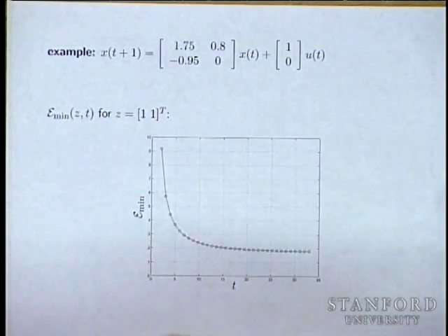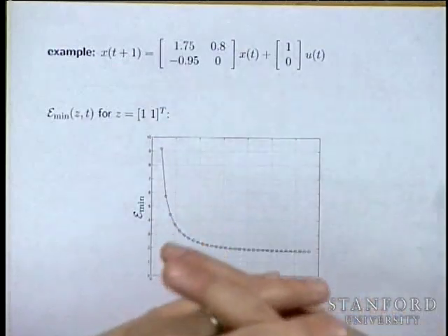If I give you like 100 steps and you have a system that's highly unstable or just unstable, if I give you 100 steps to hit somewhere, all you have to do is push x of 0 away from the origin just the tiniest bit, and then take your hands off the controls, and you let the drift, which is the unstable dynamics, bring the system out to where you want to go. Does this make sense? So you kind of work with the fact. You're not fighting the stream. It's actually on your side for reachability. Everybody see what I'm saying?